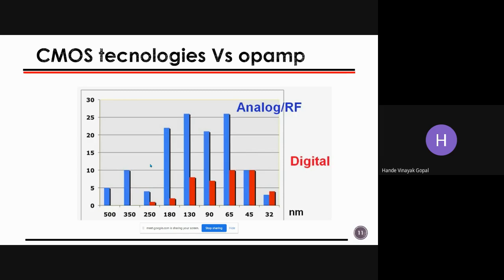as I said, for analog MOSFET we have a different or additional mask for threshold voltage fine tuning, which is not existent in digital. Apart from that, analog MOSFET has other provisions so that mismatch as well as process variation is taken care of. So if I use the digital CMOS process for designing an operational amplifier, you'll get better gain, but at the cost of some process and mismatch variation.